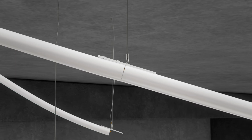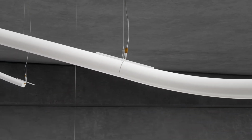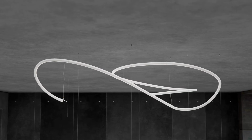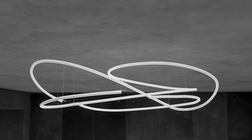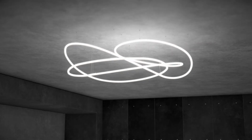Join all the elements of the light fixture using connection bars. Next, plug in the power connectors. Join all of the segments of the light fixture in an analogous way. As the last step, connect the lamp to the electrical installation and test its functioning. Bear in mind that the light fixture's mounting can be adjusted to your project.